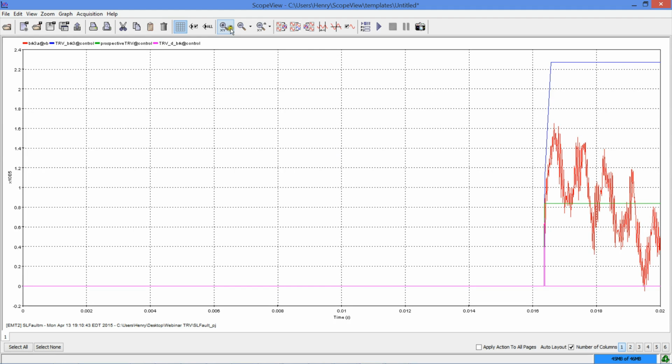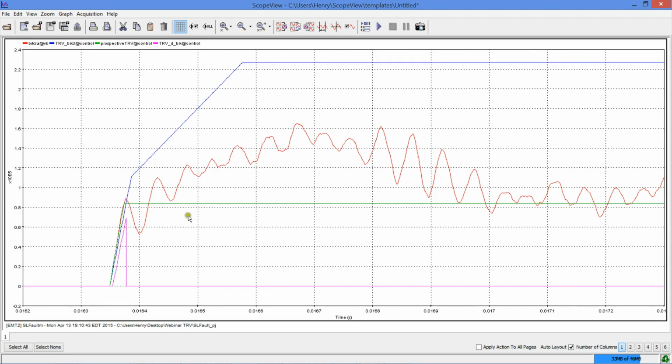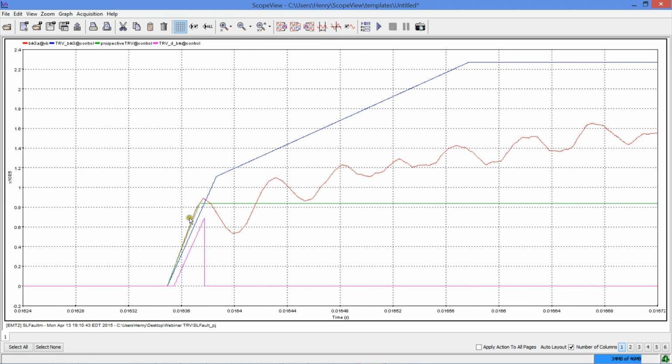Here it is. This time you see the magnitude of the overvoltage is smaller, but you will see the rate of increase is way worse. Oof, and it's actually very limit here. We go up to the TRV, so that means this breaker is definitely not the good application for this case, and we'll have to go to a higher short circuit current interruption capability.